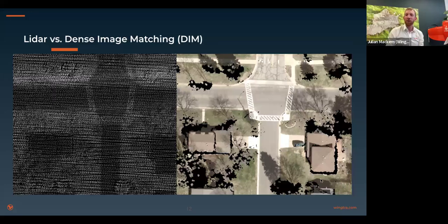Thanks, William. I have a question I want to answer here. There's several people who were asking about the altitude above ground level at which we're flying, and it really depends on how high you can fly. Ravi was already mentioning that they were thinking about doing a flight at 60 meters, and then they ended up doing it at 80 meters. We found 90 meters to be a very good sweet spot, combining large area that you can map and getting very good data.